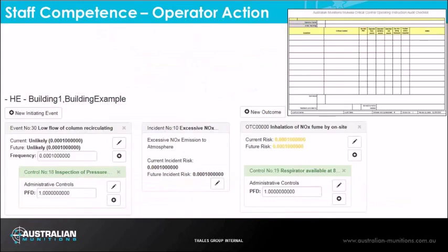In order to populate the audit checklist, we pull the operator critical actions from the LOPA. To enable the transfer of these actions into a checklist with questions, the actions must be clearly detailed in the LOPA. If a risk assessment does not contain a clear account of operator critical actions, we use this as an opportunity to update the LOPA.